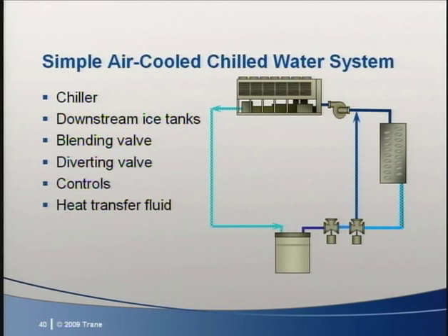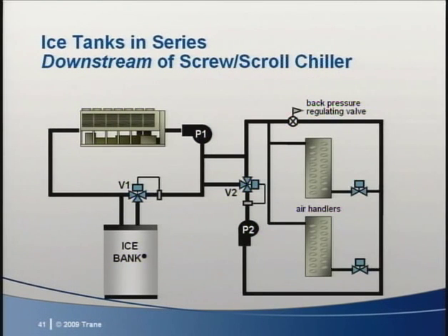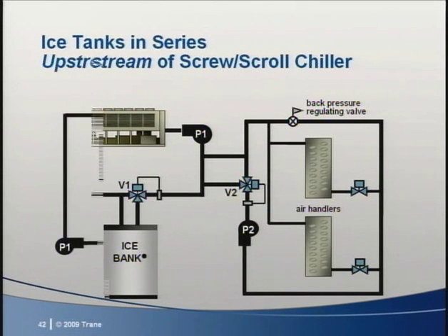Night cooling loads while the tanks are being charged will have to use the cold charge mode chilled fluid temperatures. If we add an extra pump and a tempering valve, V2, we can adjust the temperature of the fluid sent to the air handlers during charge plus cool mode. The back pressure regulating valve prevents fluid from migrating into the system during the charge mode when P2 is not operating.